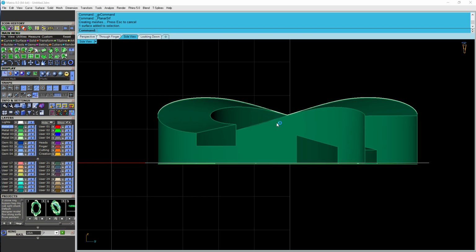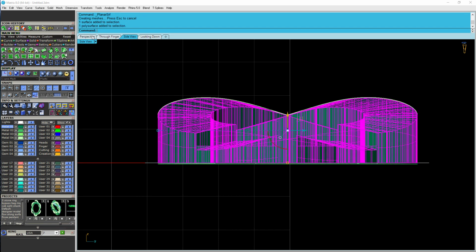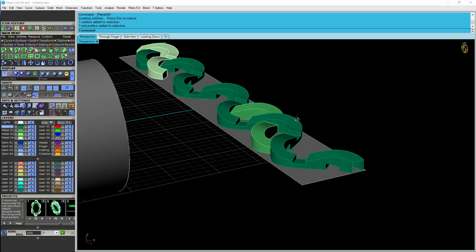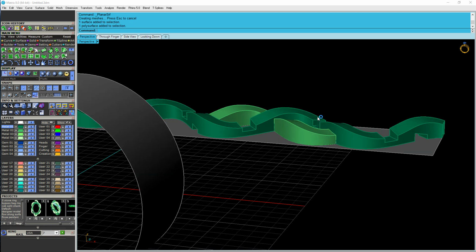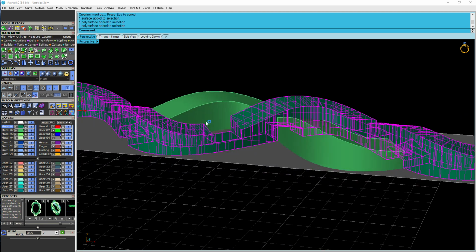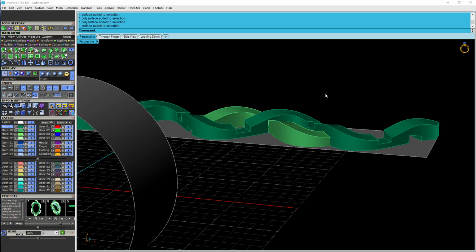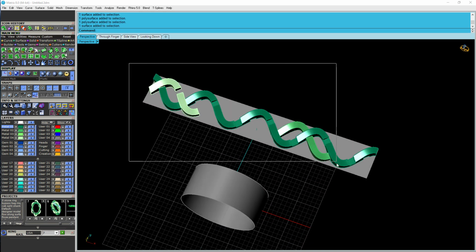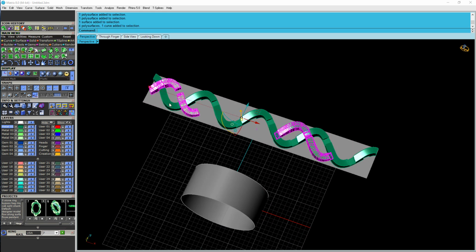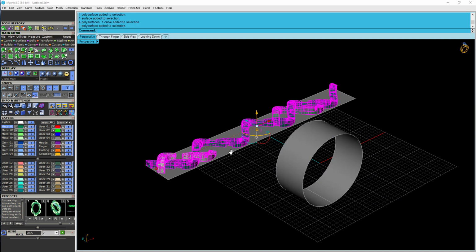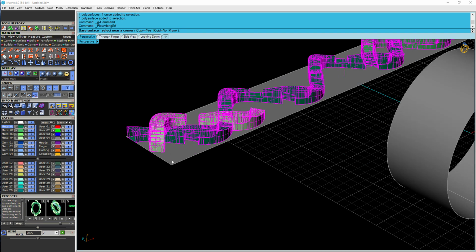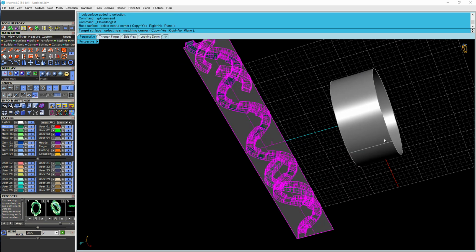Now you can add fillets if you want at this point, but I want to do the green section as gems, and anytime you're flowing gems, you want to make sure the girdles of the gems are real close to that surface, or it's going to cause a bit of distortion. It's just how the math of flowing one object to the next works. So we'll do that after it's flowed. We'll select them here. We're going to come over to transform, flow along surface, base surface here near one corner, target.